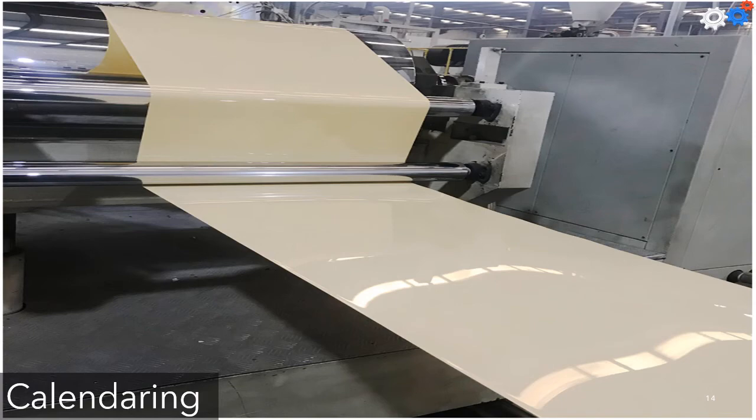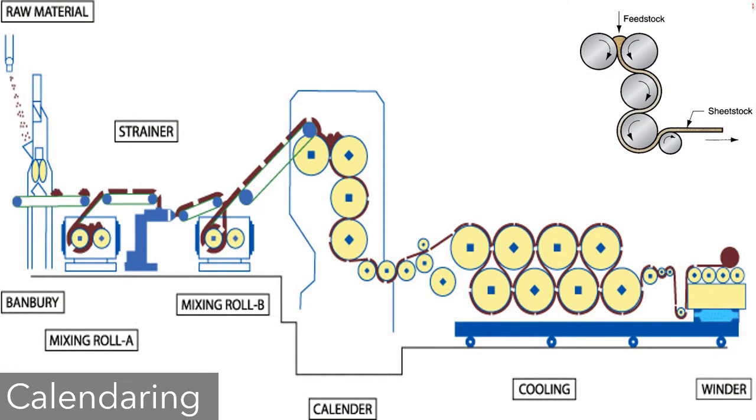In calendering, the feedstock is passed through a series of rolls to reduce the thickness to the desired gauge. Usually, it's expensive equipment, but it provides high production rates. The process is noted for good surface finish and high gauge accuracy. Typical materials are rubber or rubbery thermoplastics such as plasticized PVC. The products are PVC floor covering, shower curtains, vinyl tablecloths, pool liners, and inflatable toys.